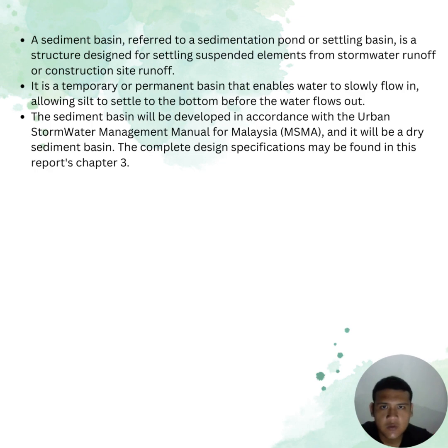Next is the sediment basin. A sediment basin, also referred to as a sedimentation pond or settling basin, is a structure designed for settling suspended elements from water runoff or construction site runoff. It is a temporary or permanent basin that enables water to flow in slowly, allowing silt to settle to the bottom before the water flows out. The sediment basin will be developed in accordance with the MASMA, and it will be a dry sediment basin. The complete design specification may be found in this report, Chapter 3.